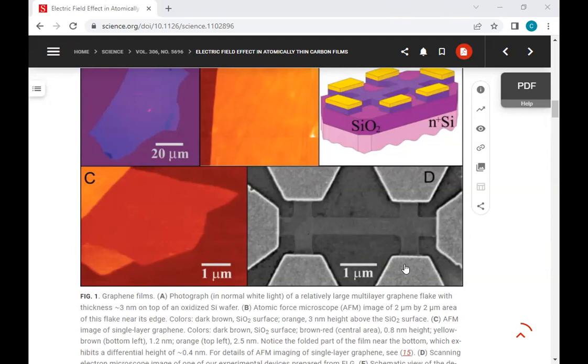But then you stick it in a magnetic field and the charges will go, let's say, in this direction. Then you can do a voltage measurement between this pad and this pad, or this one and this one. It doesn't matter, it's the same thing. That's your whole measurement. Current flowing from here to here. Voltage measurement here gives you the voltage characteristics of I versus B. And then the voltage between these two pads would give you the Hall coefficient that we're looking at.